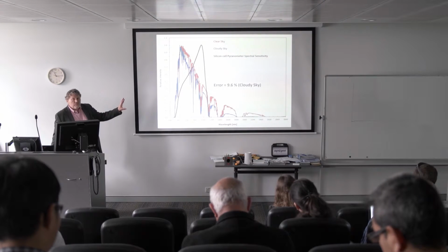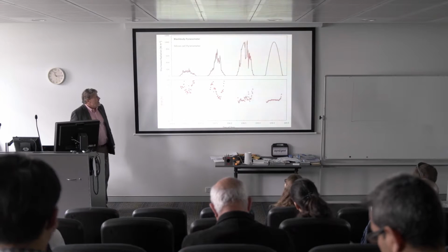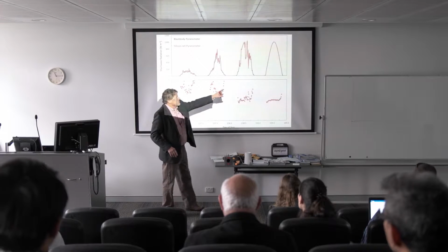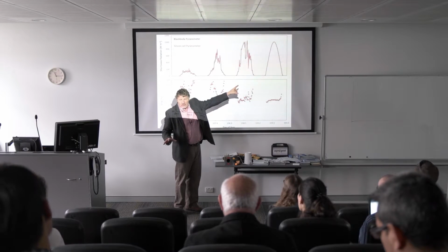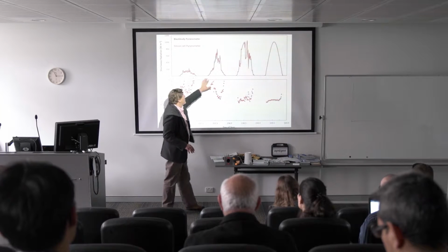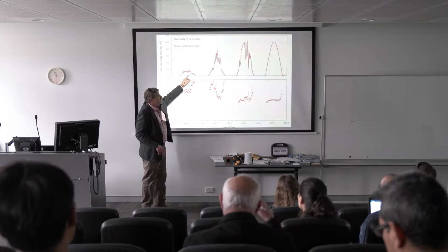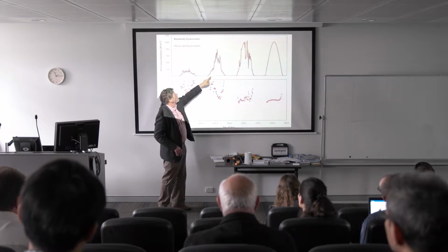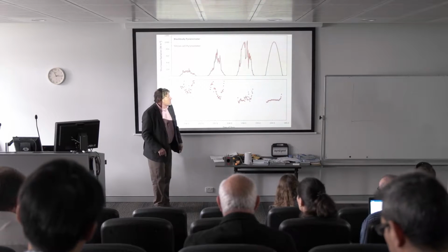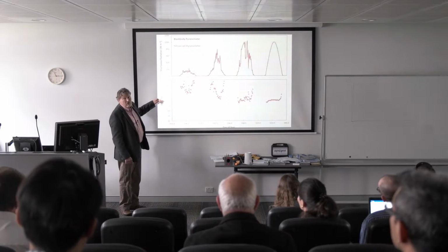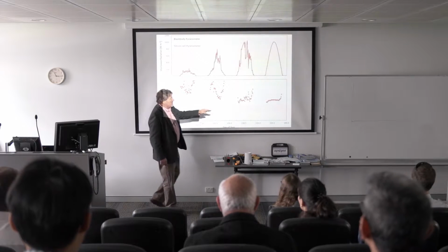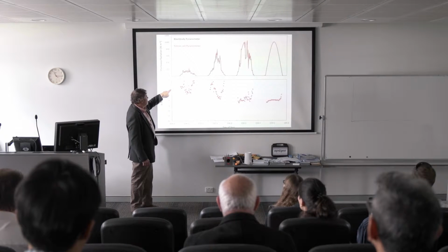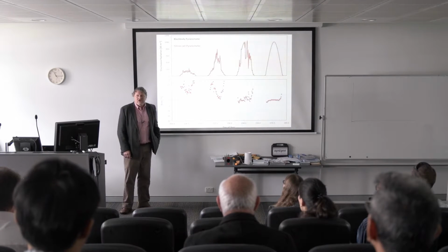Let's take a look at a couple of cloudy days in here. Here happens to be 3 days when we had full sun, which is what these sensors are calibrated to, and then partly cloudy, and then significantly cloudy here. And if you just look at this, it looks like the curves are really pretty close, the black body and silicon cell. But when you calculate the errors, almost none here, and it just gets bigger here. So here's where we're 9, 10, even times it's greater than a 10% error.